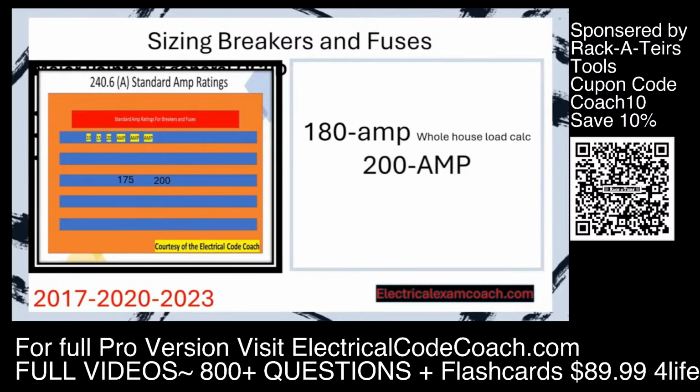But the question is what size is the service? Is it based off the rating of the equipment bus? Maybe it's a 225 rated. No, it's actually based off the size of the main breaker or main fuse for that structure. So this would in fact be a 200 amp service. The load calculation dictated what size breaker we used, and the breaker size that we used dictated the size of the service. And this is very important as we get farther into the program.